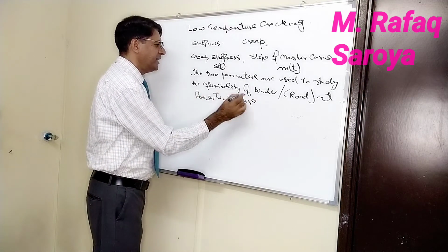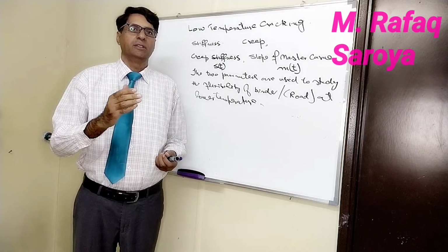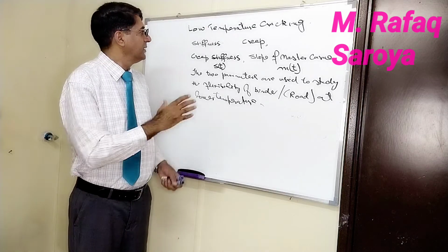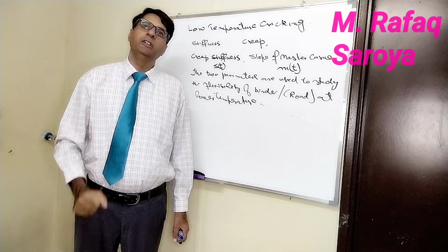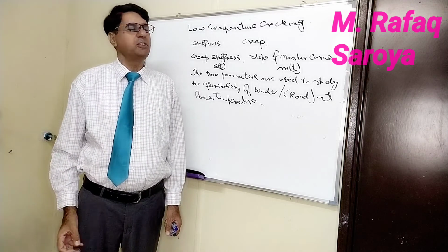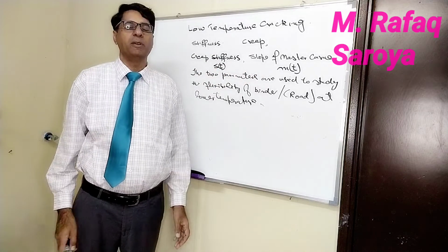Why have I written this definition? Sometimes in the interview this question is asked: what are the parameters used to study the flexibility of the road at low temperature? Its answer is just say creep stiffness and the slope of the master curve. Clear?